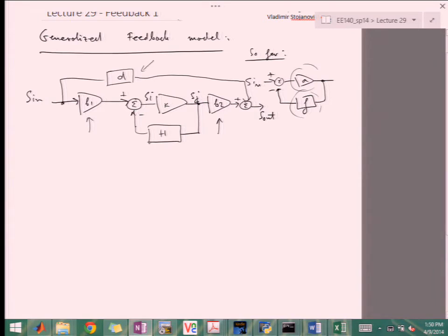And then this is the feed-forward section, which models how the signal applied to the input propagates to the output, not through A, but maybe through F. Because so far, anytime we drew the F feedback, if Rin is infinite, there was no way for the signal to go through the feedback network out. In this case, D is modeling that feed-forward behavior.